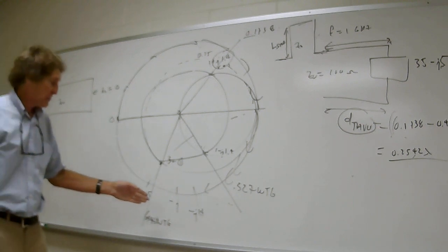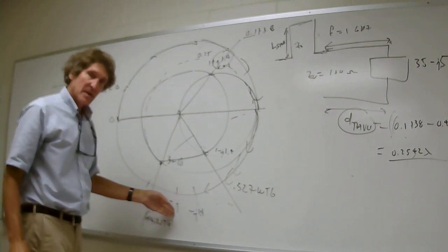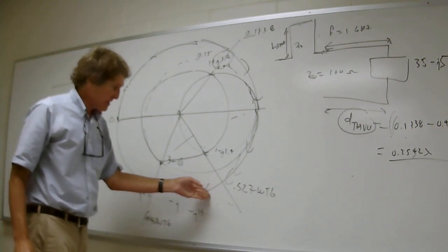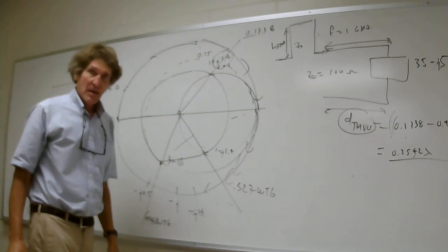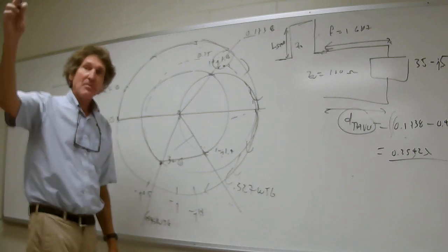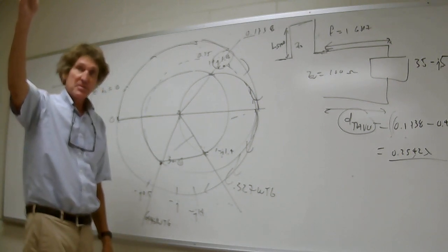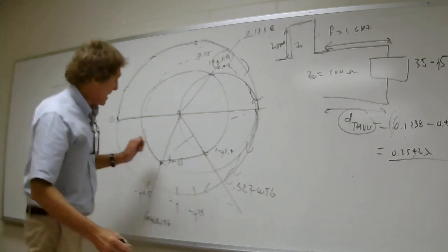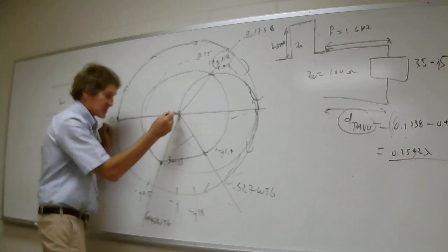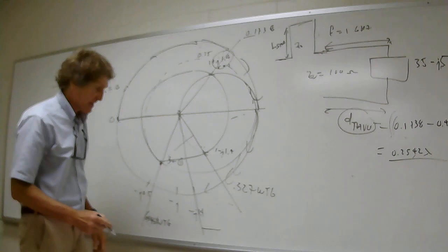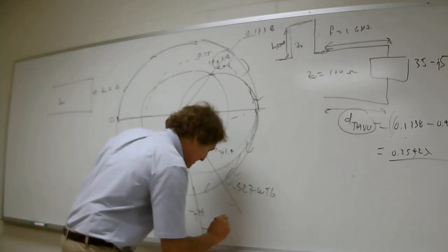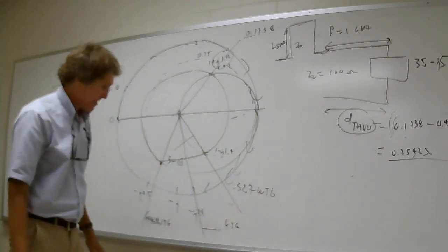This is minus j1 right here, 90 degrees down. Somewhere in here is about minus j1.4. Can you all see that? Can you see it in the back, by the way? What's the mile marker there? Now take a line, draw it straight through that, out to the edge where the wavelengths towards generator scale is, and give me that wavelengths towards generator number there.